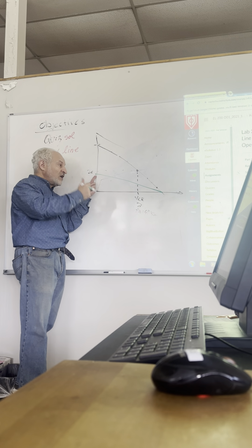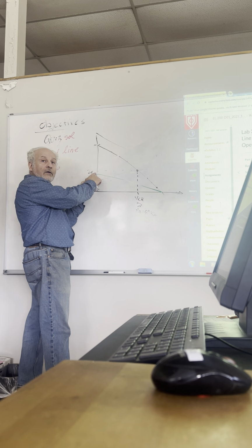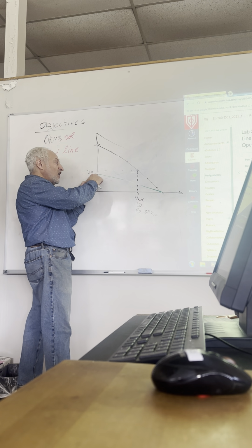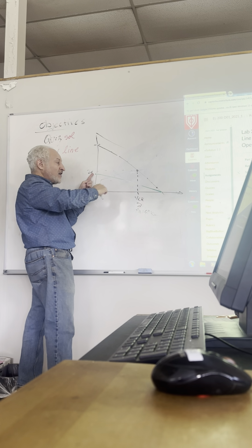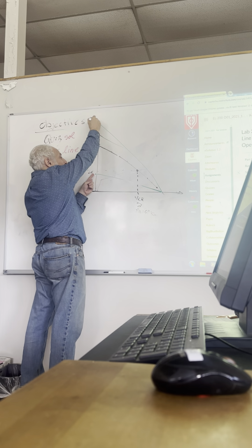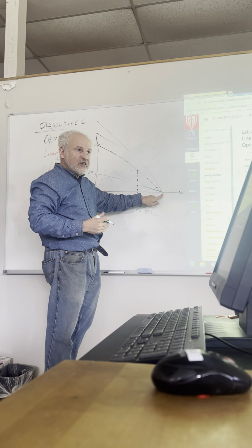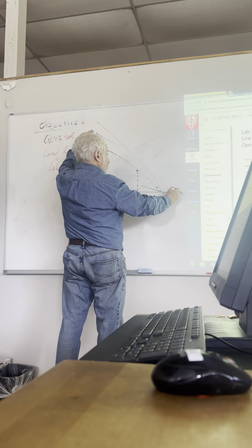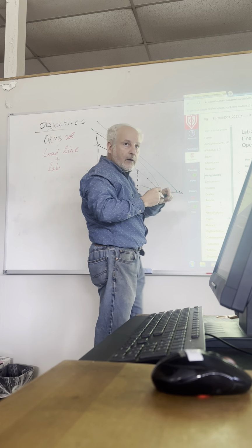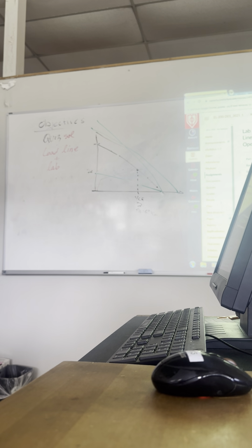If you start increasing RC, then your load line will look like this, because if you increase RC, you're not going to get as much current as a lower RC. What if I decreased RC? Well, then you're going to have a load line that looks like this, again starting from this point if you kept it at the same VCC. What if I increased VCC and decreased RC? Well, then you're going to end up here. It's up to you how you want to design it. You are the designer. You decide where you want that load line to be.